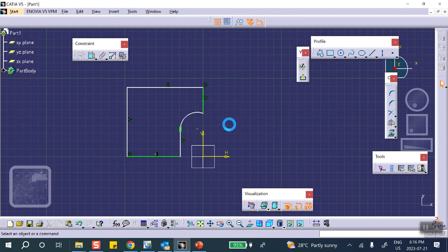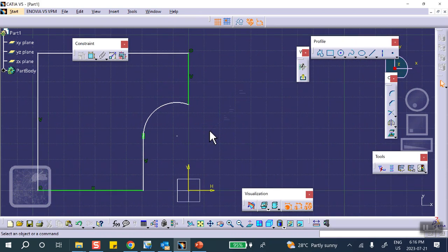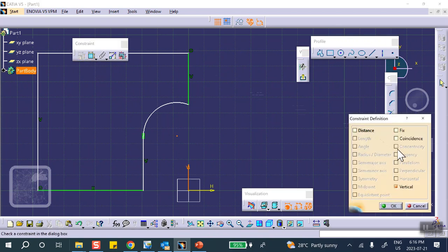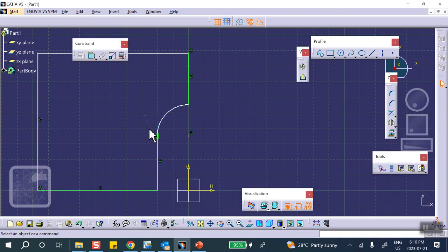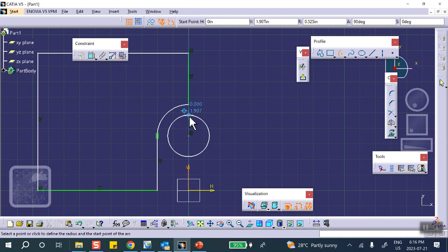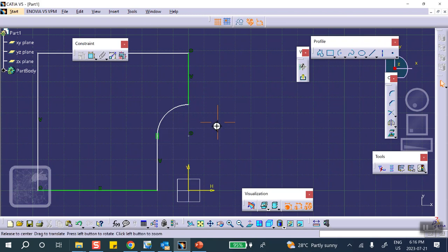There, we're going to clean it up, okay? So what do I mean by cleaning it up? So first of all, I want this point to be on that. Where is that? Control that to be coincident. Okay. And I'm pretty sure this is 90 degrees, coming in at 90 degrees. If I'm not sure, we can always check it. Let me draw an arc here. See whether it closes on it. So yeah, you can see that. Oh, cancel. Very good. Okay, good.